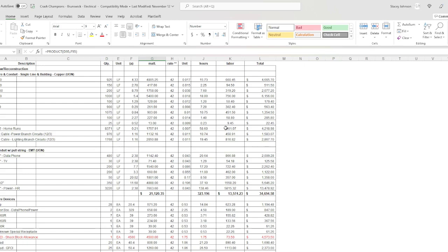Number 12 wire, you're always going to have a lot more of that, because most of the power components run with 3 number 12s. You'll run one length for the conduit, but you have to multiply that by 3 when we're talking about the home runs.